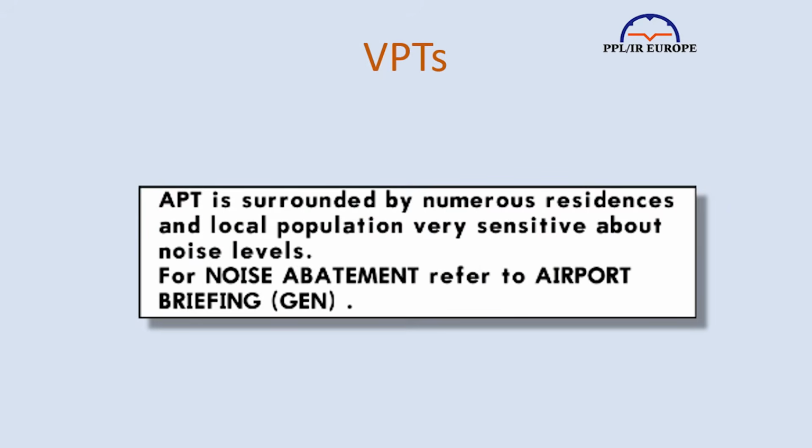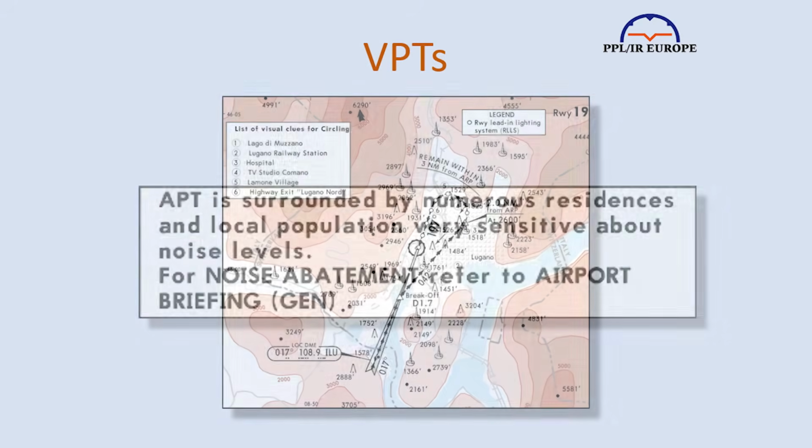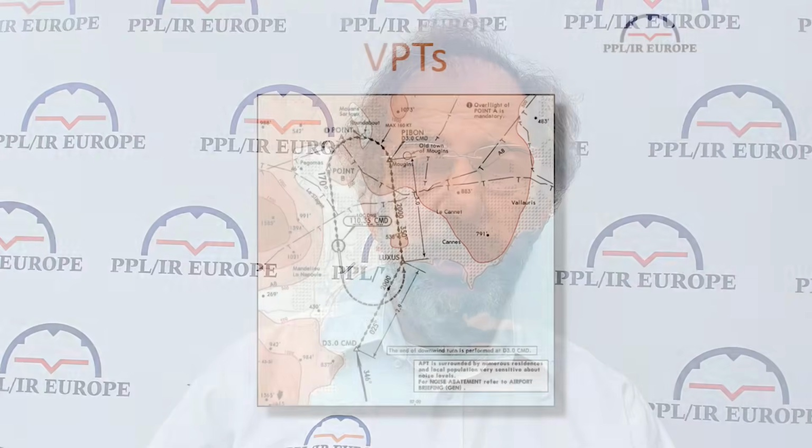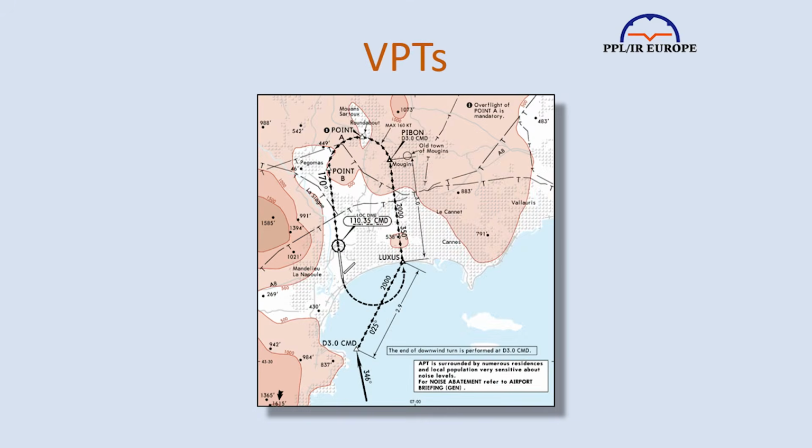I think that they are mainly used for noise abatement, but also to ensure aircraft remain clear of terrain and obstacles. They're widely used in places like India, Bhutan and Nepal for that reason, and to provide spacing from other airport traffic or nearby controlled airspace. The exact route must be followed, either depicted by specified waypoints or visual landmarks, and that route is sometimes monitored for compliance. I'm not the only pilot to have received a rude letter from Cannes, I'm sure.